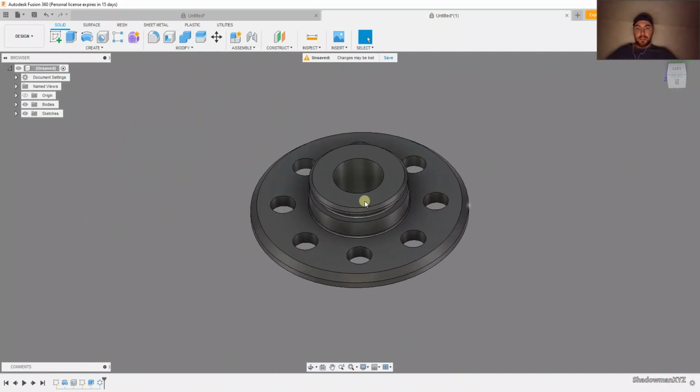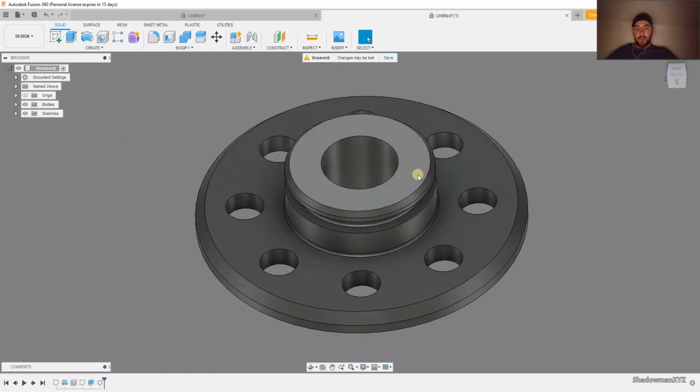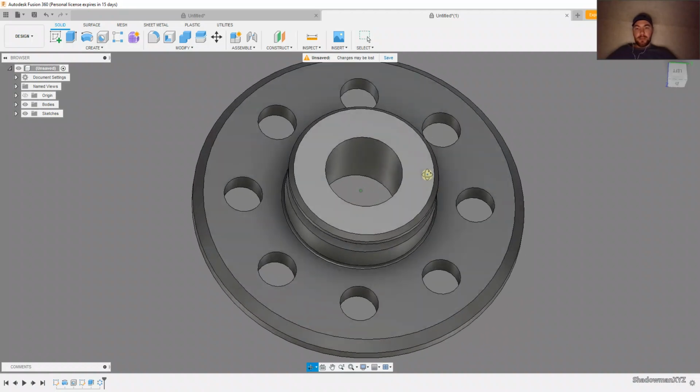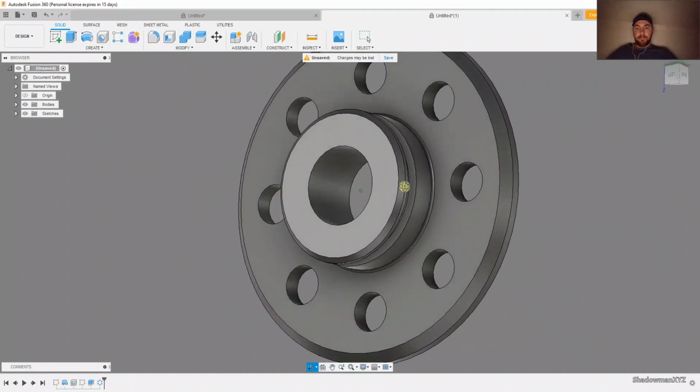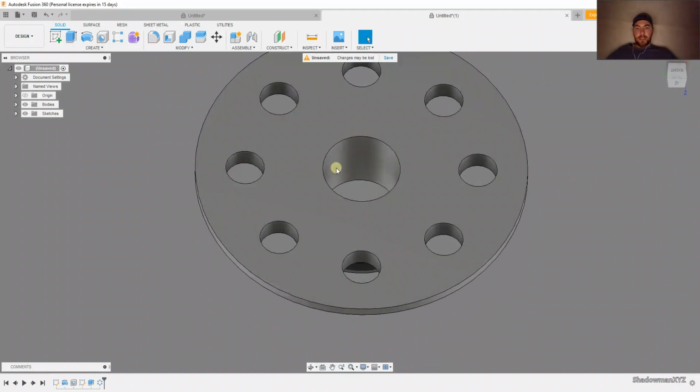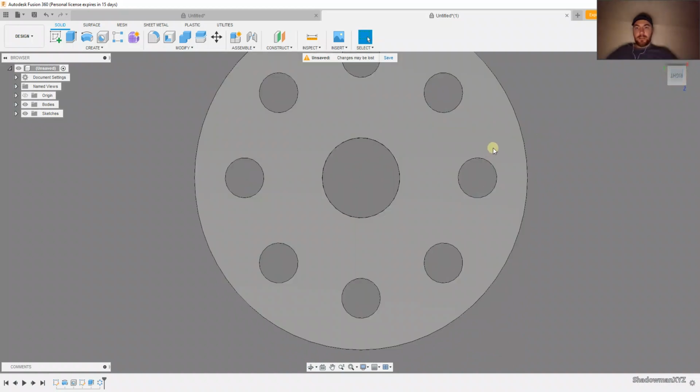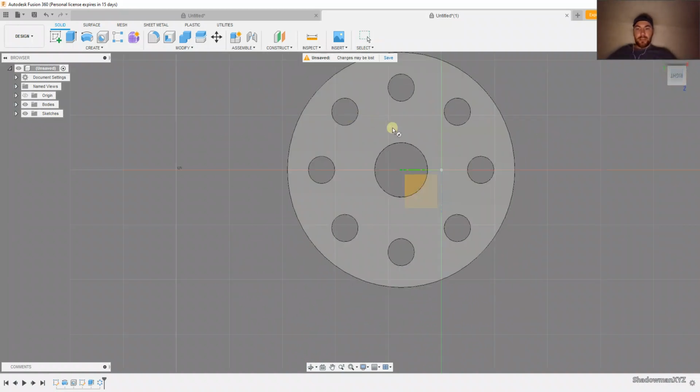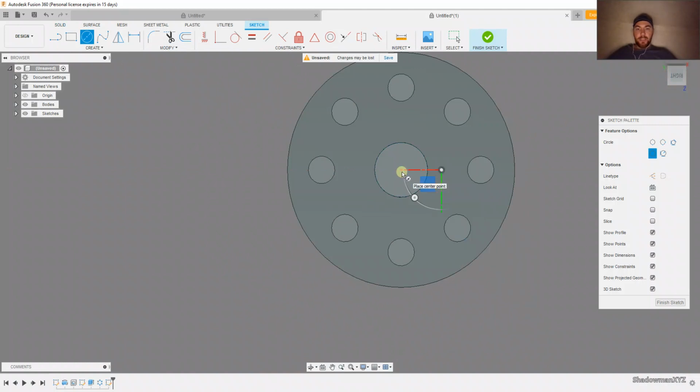Okay, now you can put bolts in there, bolt it down, looking all good and stuff. Say you want like a counterbore on the back or something. You can hit C for circle, touch the surface, find your center. See the center? It snaps right in. And just give it a definition, 1.5.